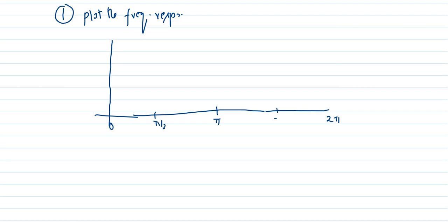Now I'm plotting the magnitude response. It goes like this. This is given in the question, this is the obvious part. Suppose this is from 0 to pi; you can even put it from minus pi to plus pi, and you will get another band. Now the first step is plotting the frequency response, and you'll always take the full region 0 to 2 pi.